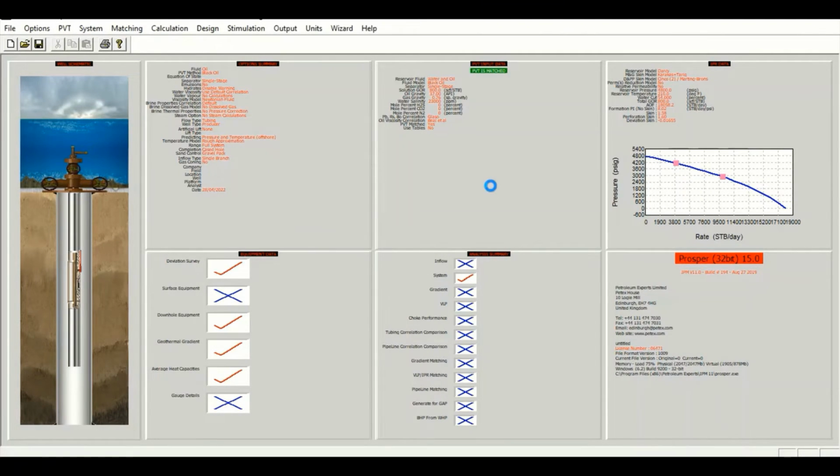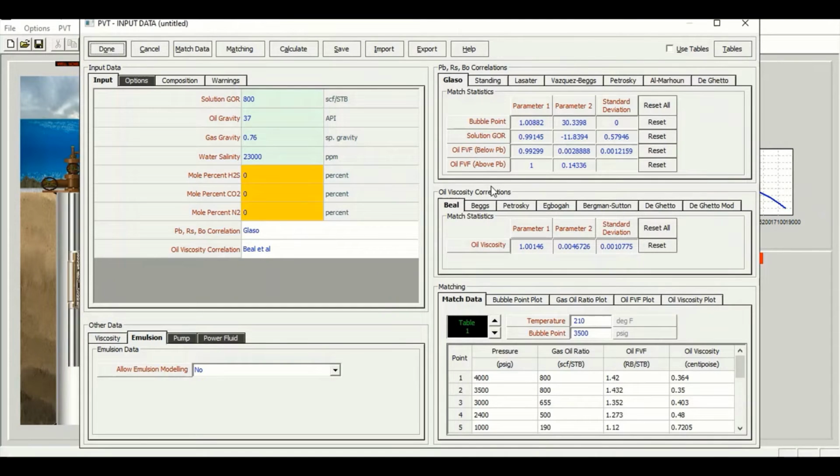And let's say after the water cut increases, now the salinity of the water increases as well. Previously, the salinity is only 23,000, but right now it's 180,000 ppm. And with this high salinity, we fear there will be problems, because maybe the salt will deposit and create scaling inside our tubing. The salt will deposit and it will block the wellbore because the salinity is too high.